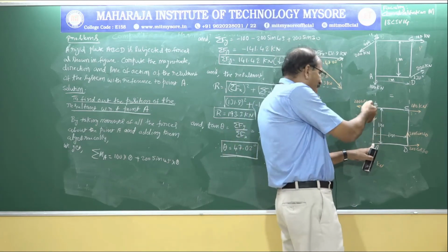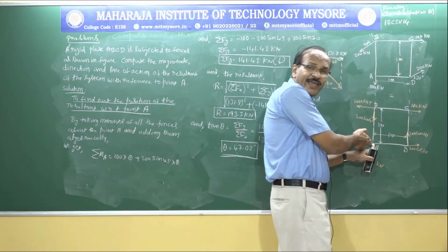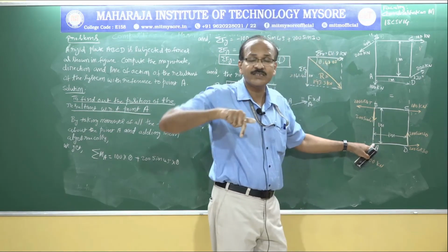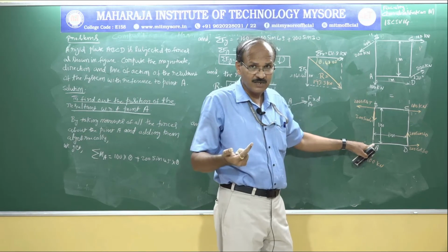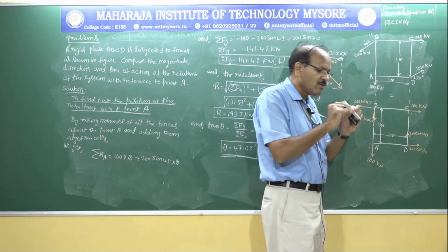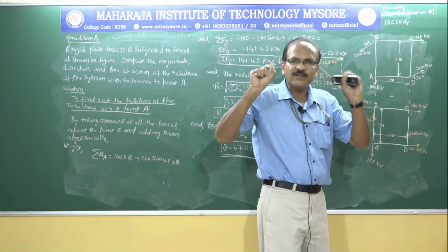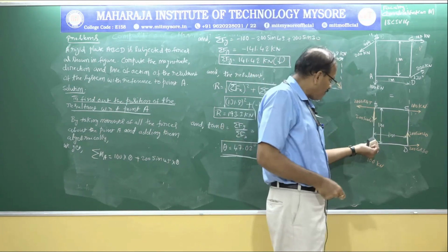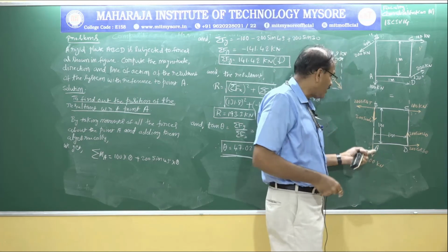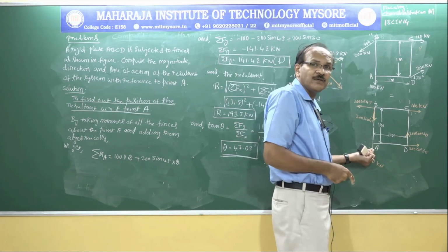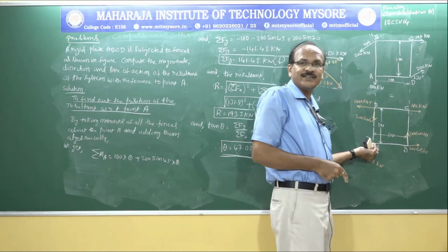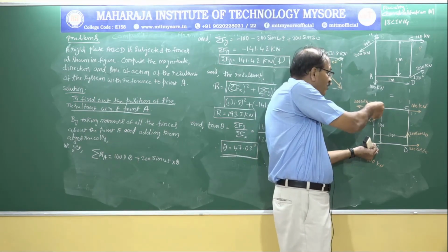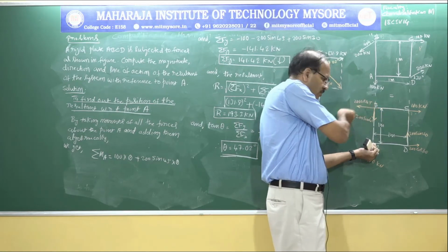So I need to consider this 1 meter. And what is the kind of moment this force is causing about A, in which direction, clockwise or anti-clockwise? For that, you have to imagine a thread of length 1 meter, that is this distance. Because you are trying to find the moment of this force about this point, keep one end of the thread here and take the other end of the thread which ends here and move in the direction of the arrow.